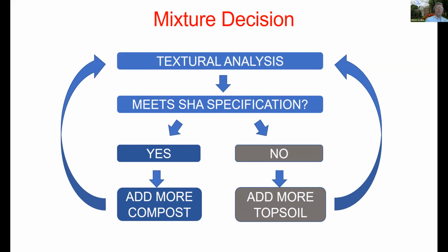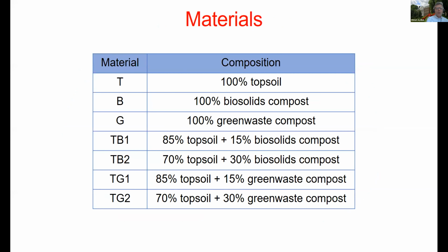So what we are trying to do here is look at the textural analysis. On top of that, pH and organic matter have certain requirements. Obviously, by adding compost, we will be increasing the organic matter content significantly. So that kind of goes outside of the specifications, and the local agencies are aware of that. But the pH requirement is important. Neutral pH, remaining anywhere from about 6.5 to 7.5, is highly recommended for this region. And I could imagine that it could be for other regions.